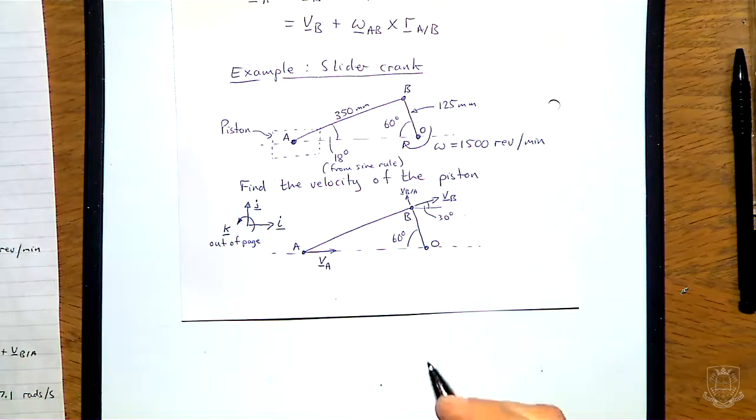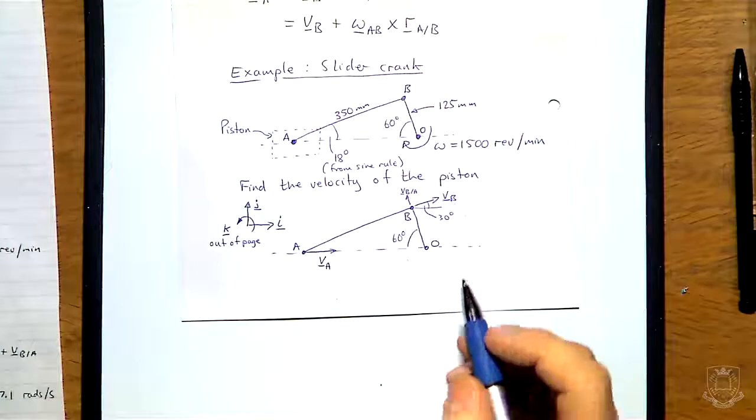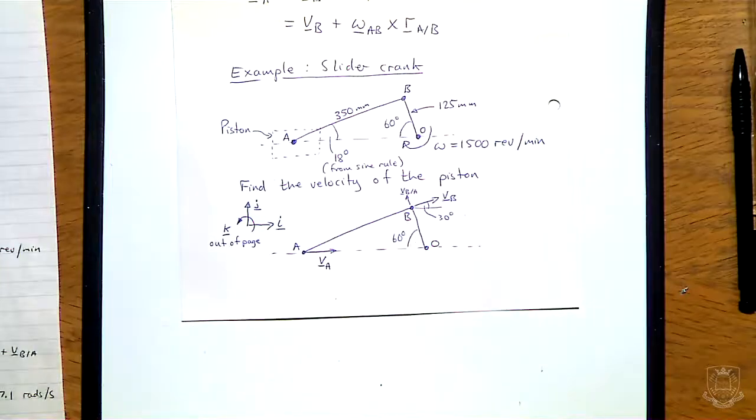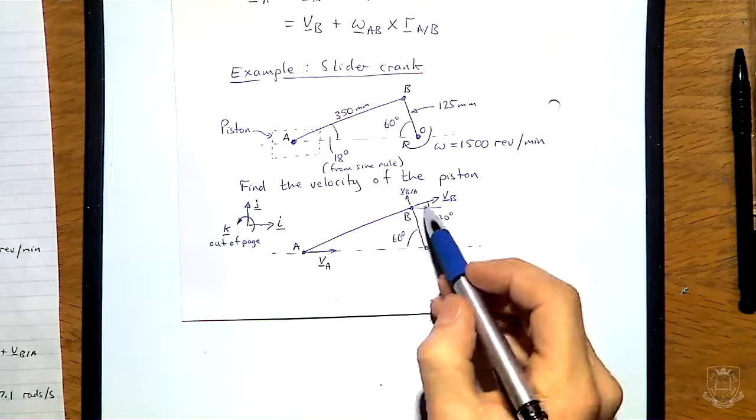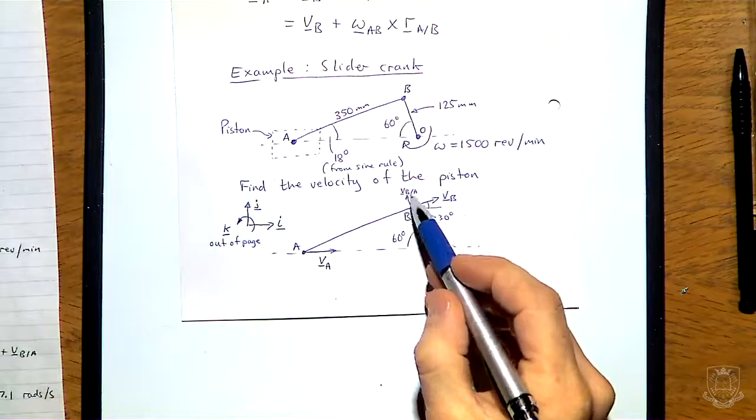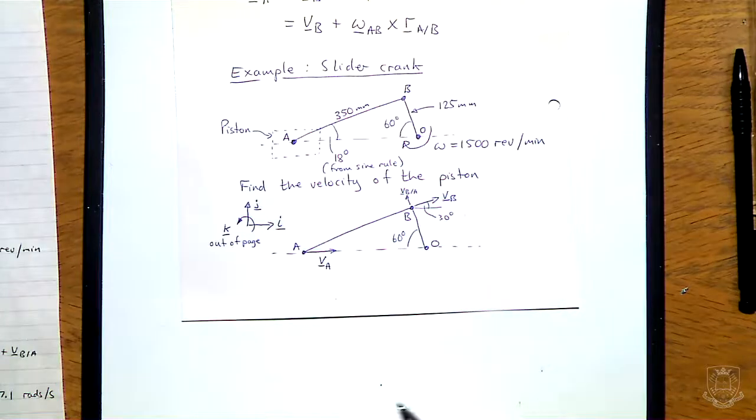If you think about what's happening with this motion, I know I'm freeze framing it, but think about what's going to happen in the next second or so, as the crank rotates to the right, this thing is going to be moving up and around. And in fact, what we'll show in this analysis is that we can treat that as a circular motion around this point A. In which case, this VBA is also moving like a tangent on the circle of motion.